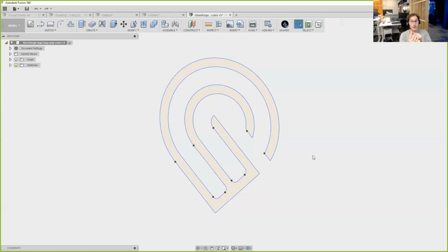And uploading the DXF was pretty helpful. Actually, I don't see any problem with that at all. But of the 4 options, my personal favorite is still going to be insert SVG into Fusion. And so I recommend you give that a shot.